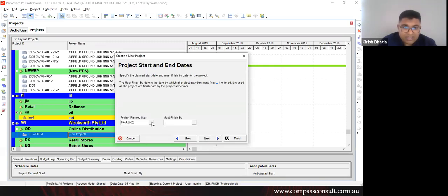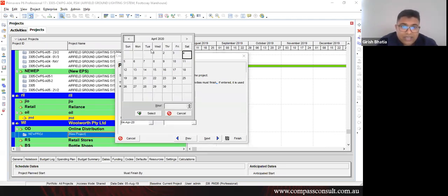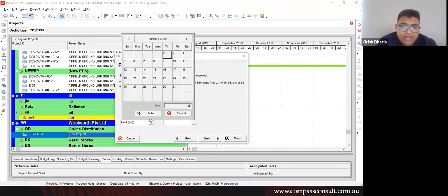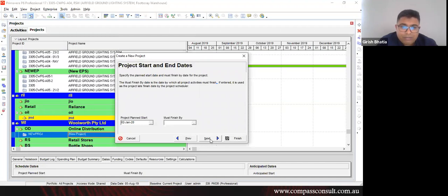So what is the project plan start date? So yes, this date can be any date in the future. This date can also be any date in the past. So let's say if a project has started on 2nd of January and I have been introduced as a planning manager now, and the company wants me to make a plan for them. I can go to a back date. Let's say 2nd of January, select and do the project planning and make it a project plan start.